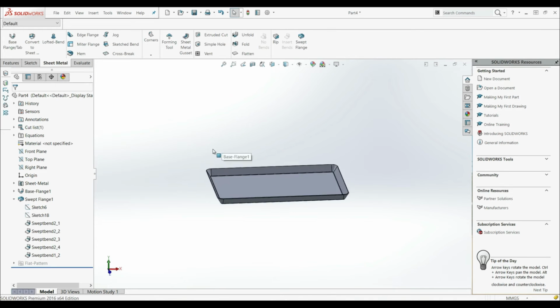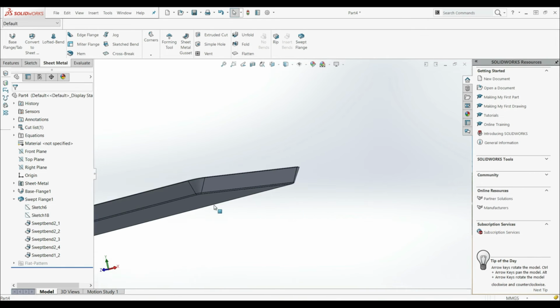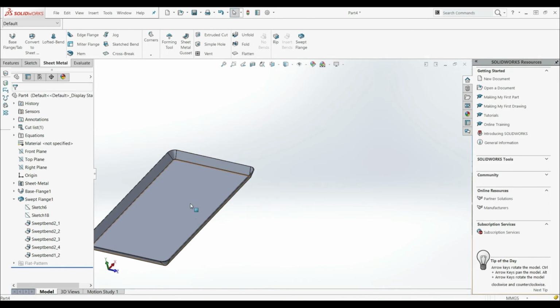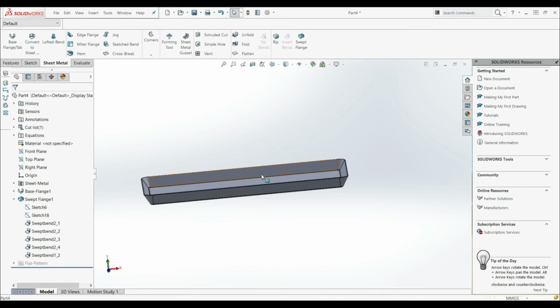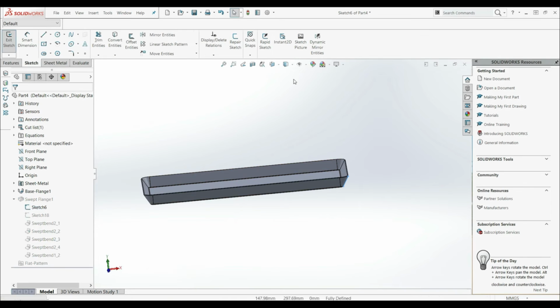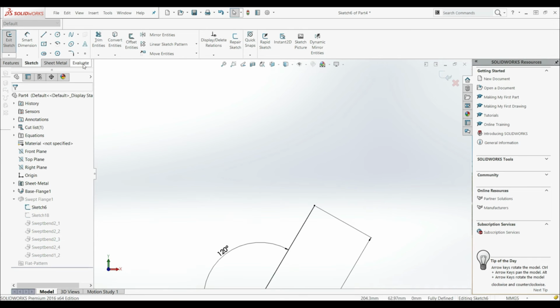And we got this result. As you can see, our corners are rounded. This one here, all 4 corners. So we don't have any reliefs in the corners. We can also create some more complicated profiles. So let's go to the sketch, Edit Sketch, normal to. Let's go here.